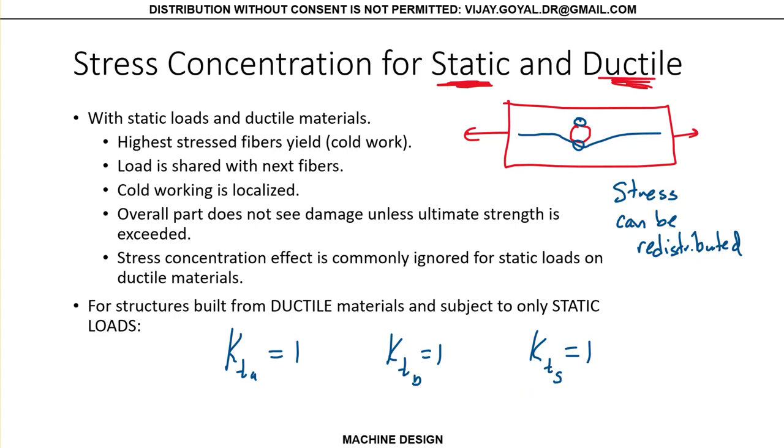Now, I want you to consider this. I want you to think about this. I have a structure that is a three-dimensional case, right? It is a state of stress that has 6 unique stresses, as you know. So it has sigma xx, yy, zz, tau xy, xz, and yz. And typically we end up with plane stress, as we mentioned. So we only end up typically with three unique stresses, right? Typically, that's what you end up with.